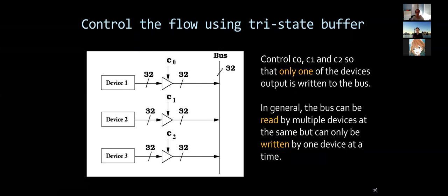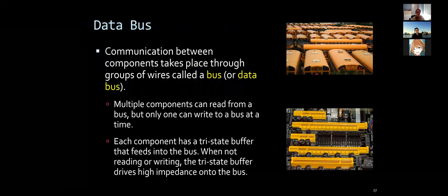So you have that shared infrastructure that allows multiple reads at a time, but not multiple writes. Usually that's a good trade-off because writes are more rare than reads. We typically read more than write from memory when we execute an application. But obviously, if your application has too many writes, you're going to be bottlenecked by the bus. So the bus at a time can only write one item.